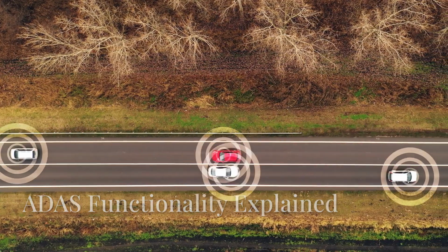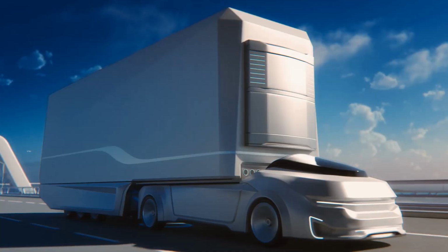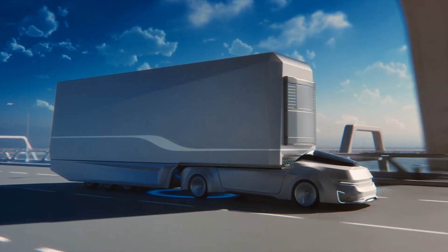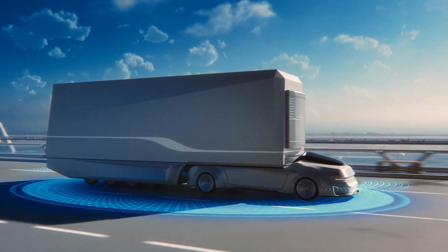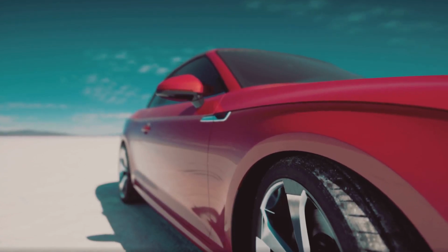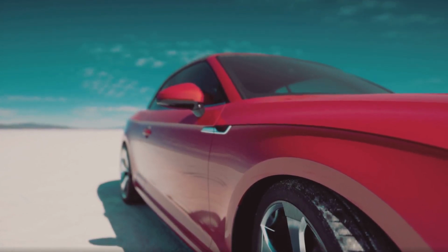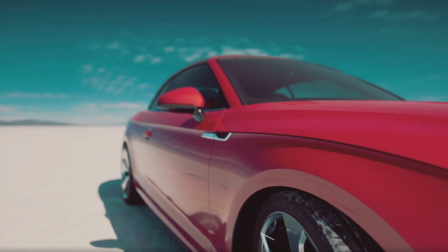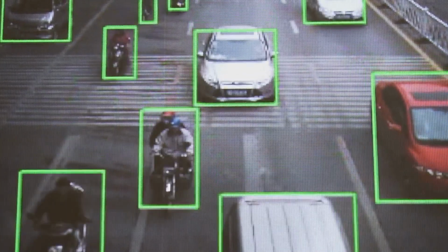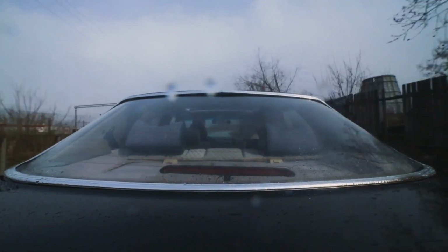ADAS, or Advanced Driver Assistance Systems, works by using a combination of sensors, cameras, radar, and software to monitor the vehicle's surroundings, interpret the data, and provide real-time feedback or control. Here's a breakdown of how it works. 1. Sensors and cameras. ADAS relies on multiple types of sensors and cameras to collect data about the vehicle's environment. These sensors can include cameras, which are used for detecting lane markings, road signs, and vehicles ahead. They provide visual data to the system.